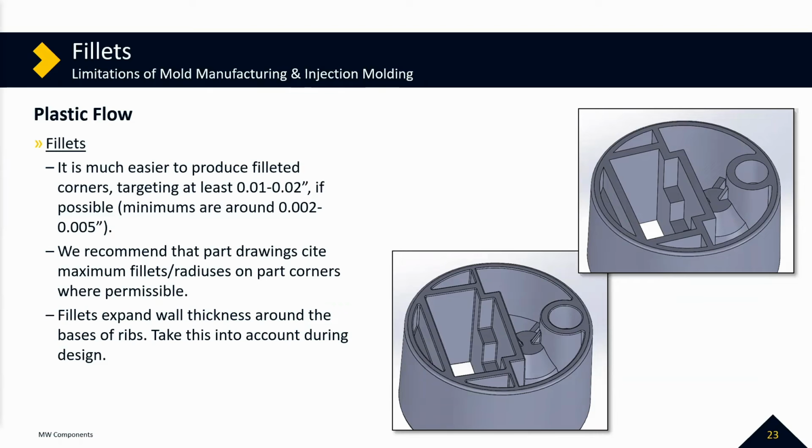That's something you really need to take into account when you're thinking about, oh, well, how much can I fillet these areas versus these other ones? Can I fillet where my ribs meet my wall if the opposite is an aesthetic surface? And should I be redesigning my ribs to a lower thickness then to compensate for that? And so it's certainly something to consider as you're moving through the design phase.